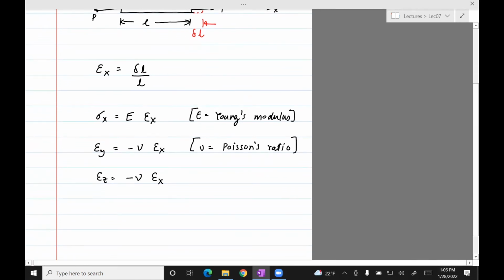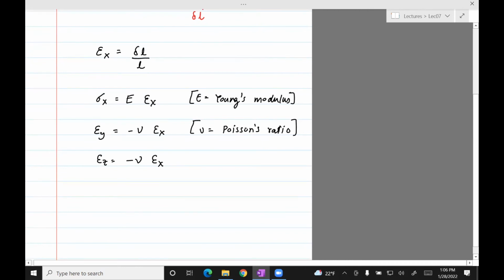Okay, that's also a material constant. There is a foam which actually has a negative Poisson's ratio, which is kind of interesting: if you stretch it in one direction, it also expands in the y and z direction. So you can actually search for materials with negative Poisson's ratio. They're kind of interesting. They defy our understanding of how normal materials behave.